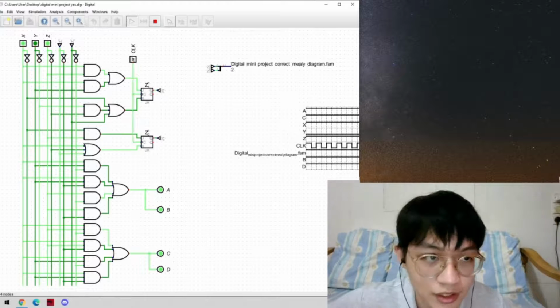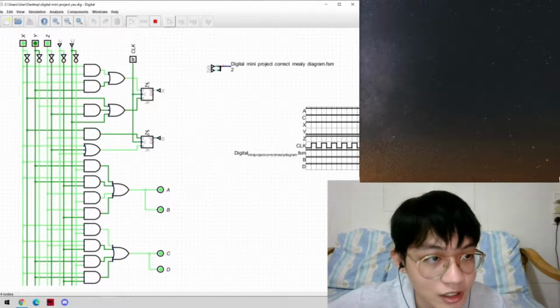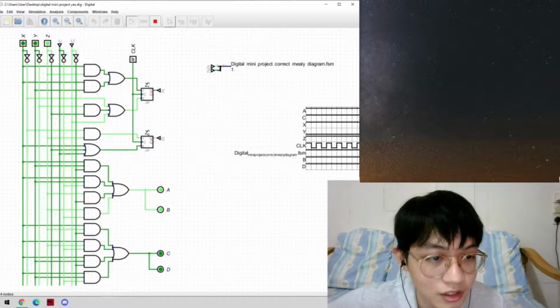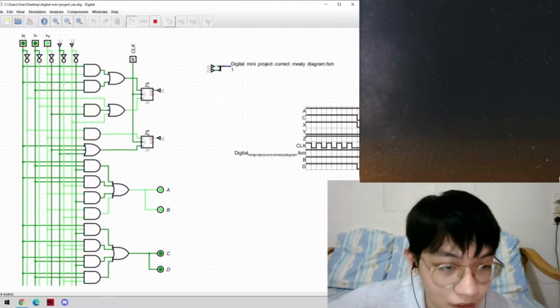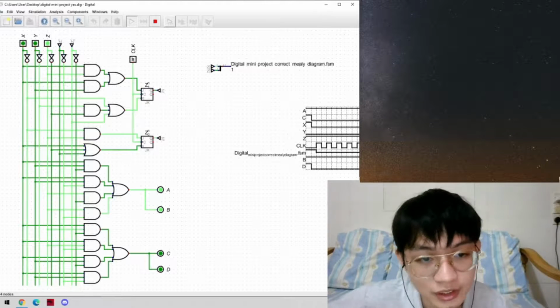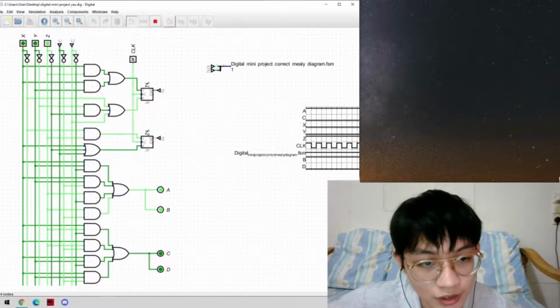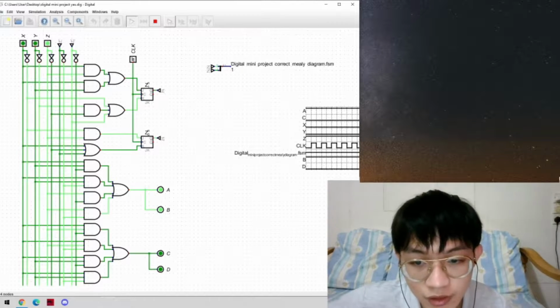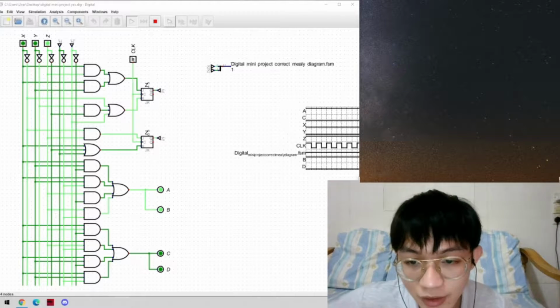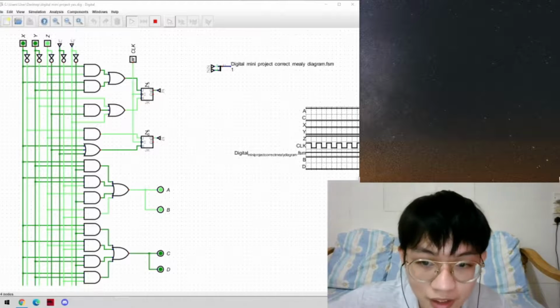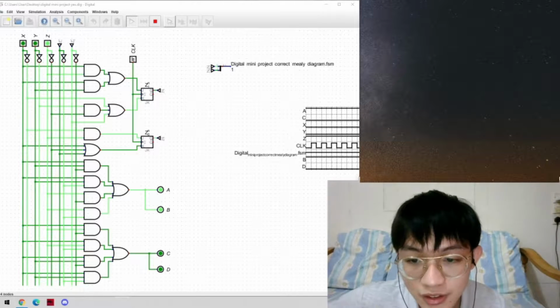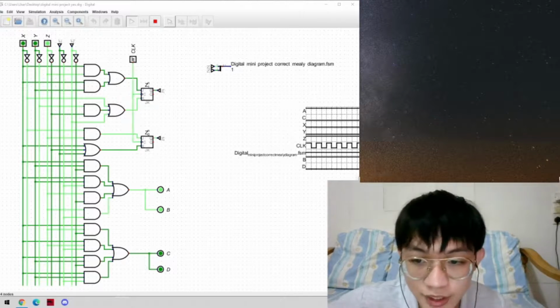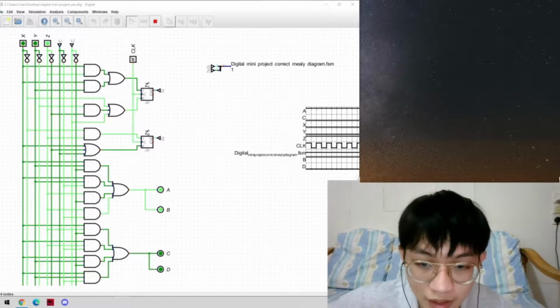Afterward, the heat detector is deactivated. It goes back to the warning state, in which only the two outputs, the siren and the warning light, are still activated. So even if the heat detector is deactivated, the alarm will not turn to the normal state yet because the CO is still there, to warn people they are still in danger and better not get close to it.